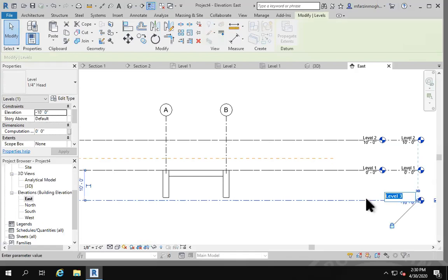The basis of the foundation level is that it's usually between 3 to 4 feet below the freezing point if your level 1 is at ground level. If you have a basement, the lower level of the basement is about 3 feet below that part. But usually when you put it on the first level, you have to have at least 4 to 5 feet below the freezing point.